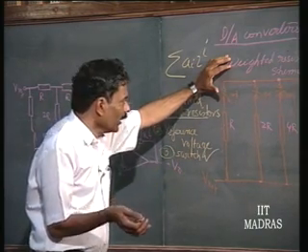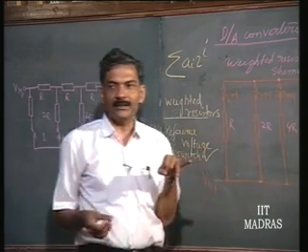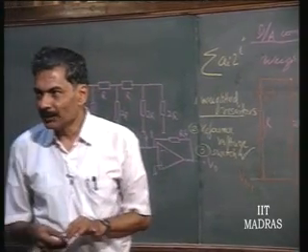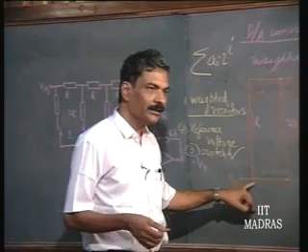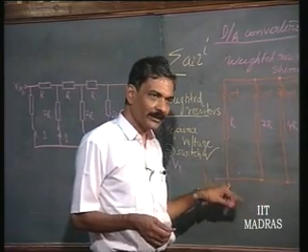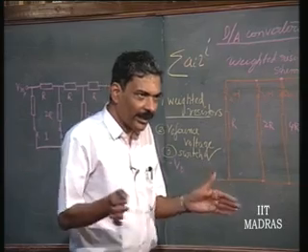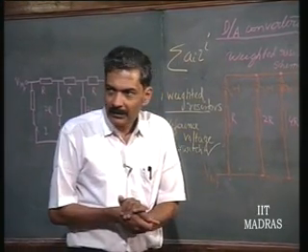So, not only that, you would automatically notice that now the V reference is giving a constant current irrespective of the switch position, and therefore, even if there is some output impedance, it is going to result in a constant error rather than a random, changing, time dependent error. Okay.